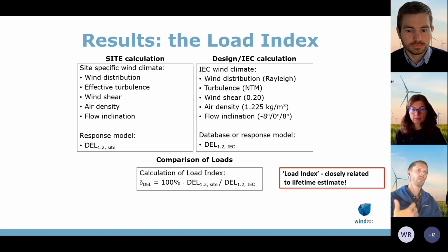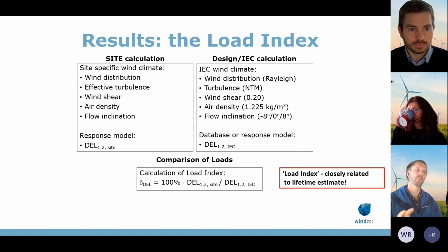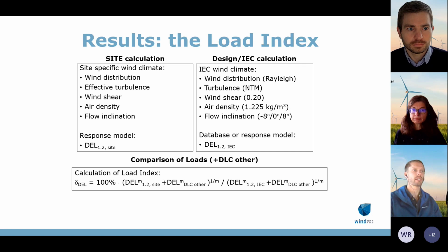So, I promised you lifetime, and I'm still talking about loads, but that's because there's a very close relation between the load index and the lifetime, and I'll get back to that in a couple of slides. I just want to mention, because I also mentioned before that we include the other design load cases, what we call DLC other, this is just showing you how these are included in the calculation of the load index. The factor M here is what we call the Wöhler exponent, which is a material parameter, and I'll get back to that a little later.